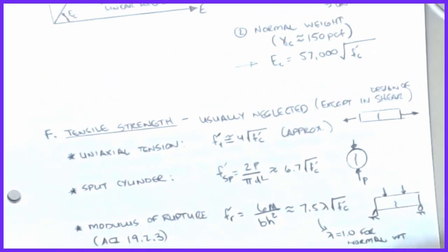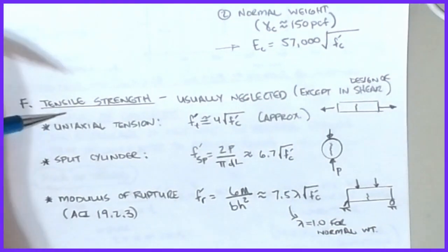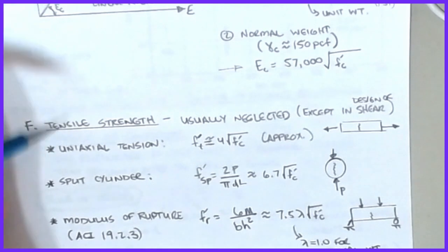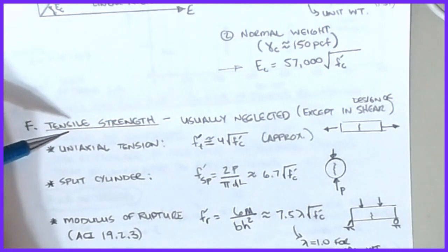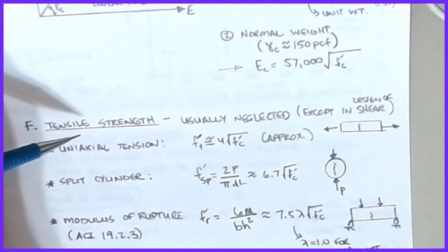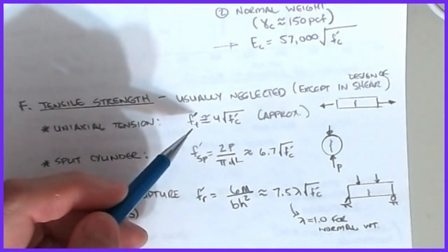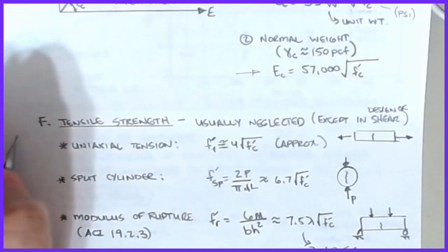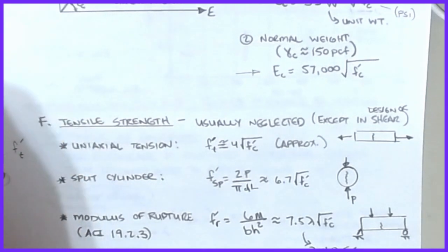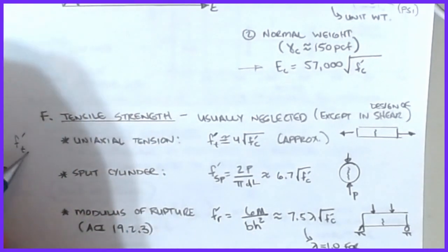Now, again, we talked a little bit about the tensile strength of concrete, something we're always keeping our eye on. It's a significantly smaller value than the compression limit. But this is also what's driving where our steel needs to be located, or where the steel bar's positioning needs to be. So we're constantly looking at the different loading cases that produce tension in a particular element. So for tension, it's now an f't value. And again, in concrete, when we get into the actual design, we're pretty much going to be neglecting this because these values become so small.